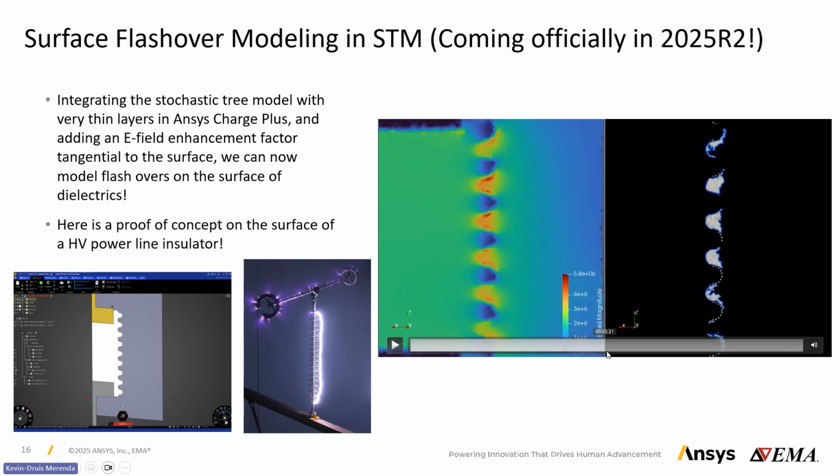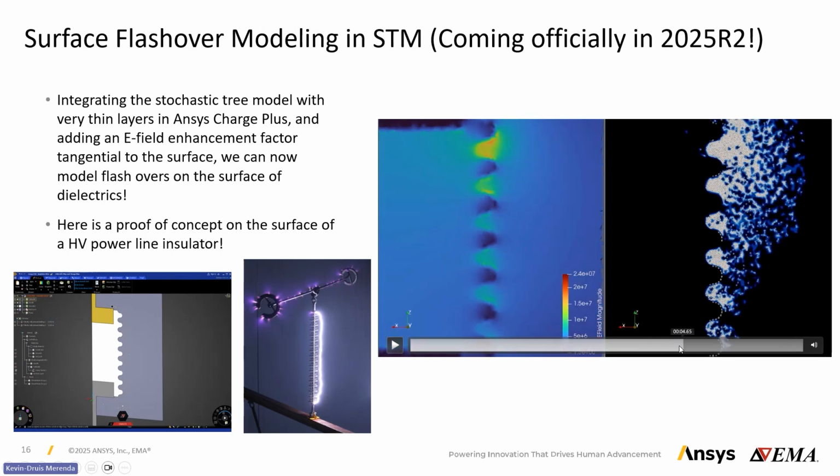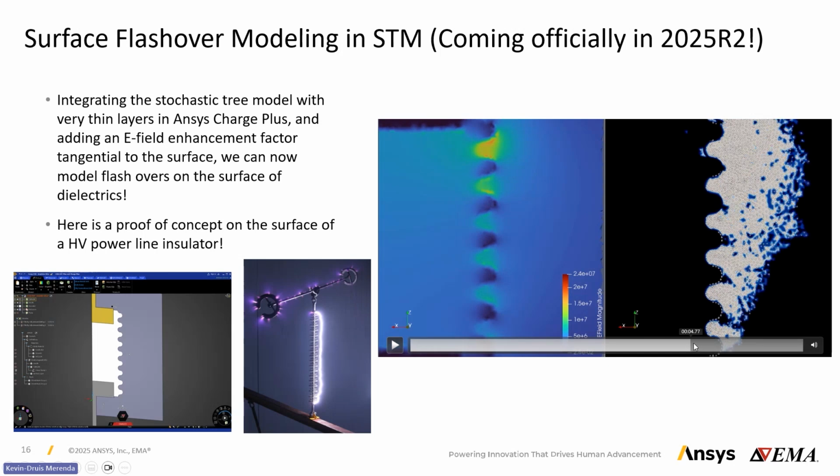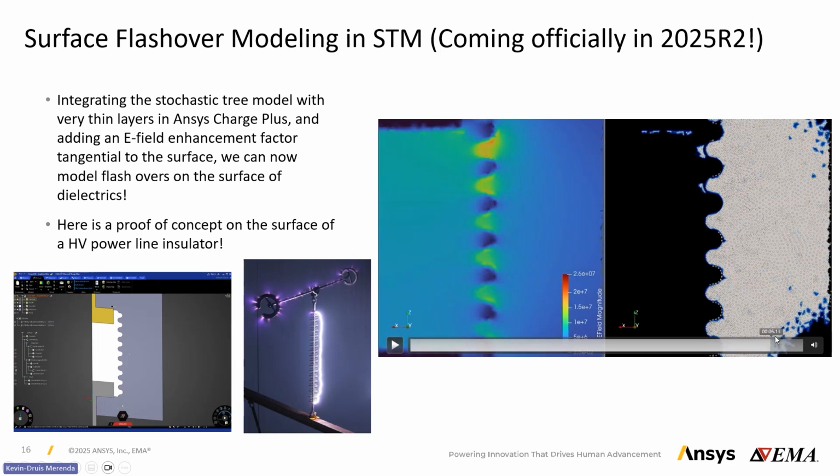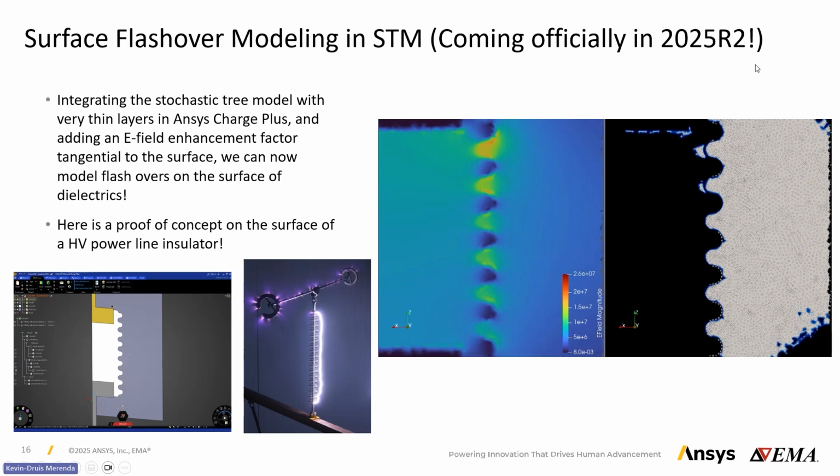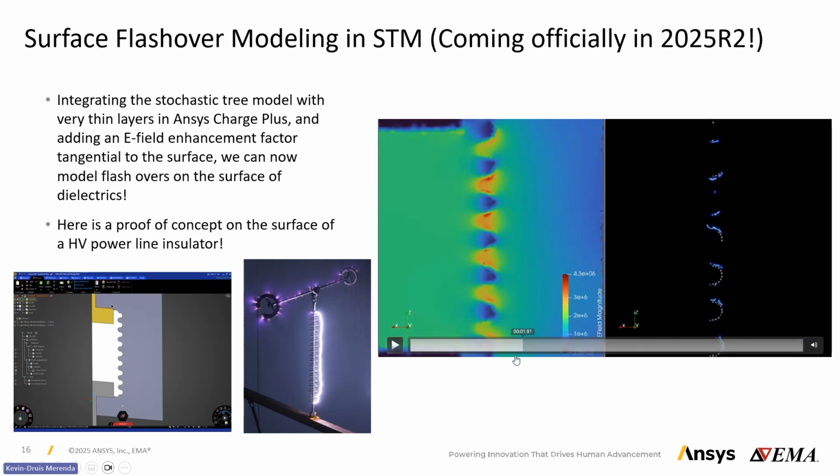And then slowly we are getting more and more arcing nodes, and we're able to understand we're ultimately changing the whole field distribution and arcing the whole air around the system. This is why you're seeing it kind of blow up and get the whole air arc, just like you see in the image on the left where the full arc is established. What we really care about is typically trying to stay away from any of the first nodes that are contributing to the discharge process.